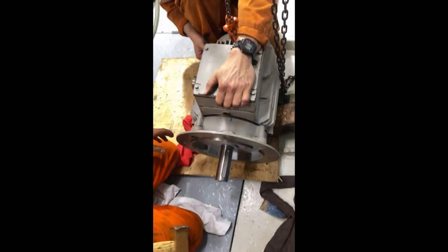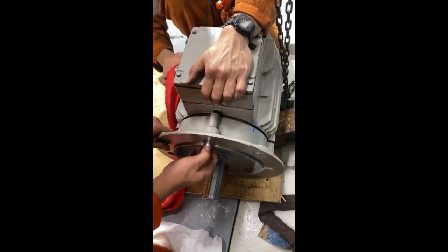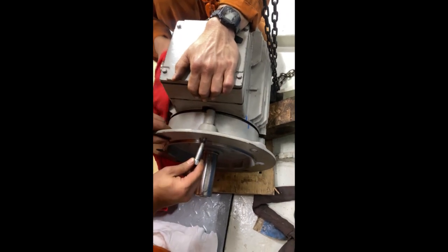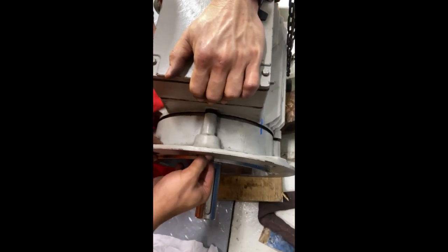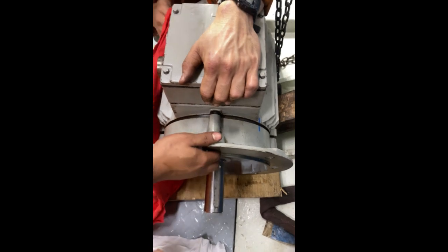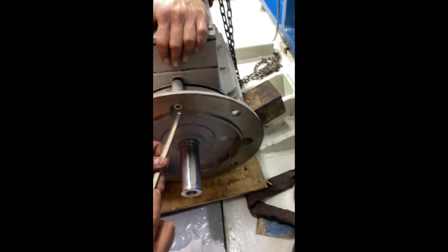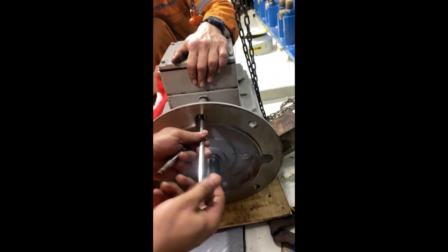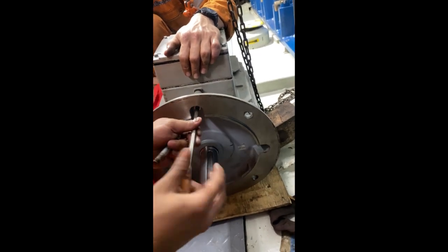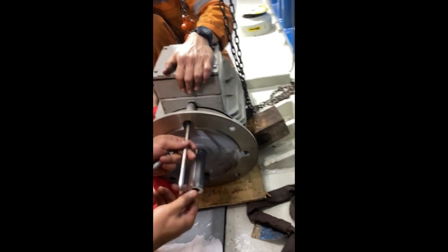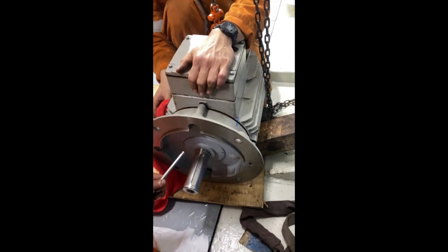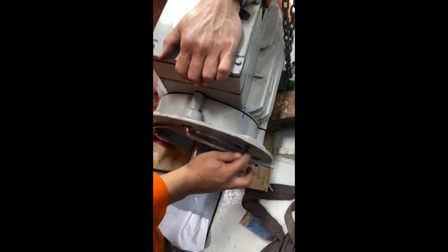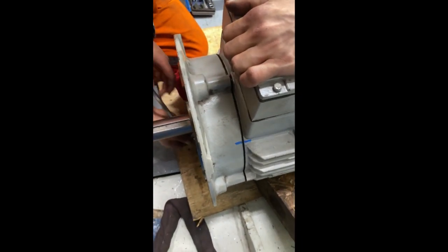When the bottom plate is already close enough to the thread, use the securing screws and tighten them equally so that the bottom plate will just slowly slide onto your bearing housing properly. Now tighten all 4 screws.